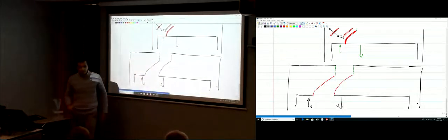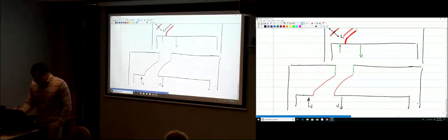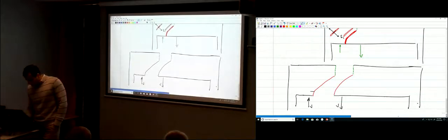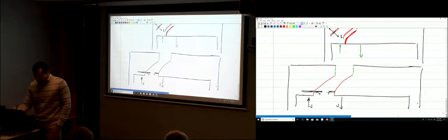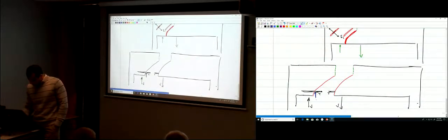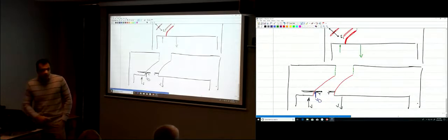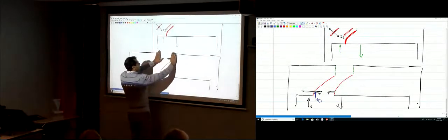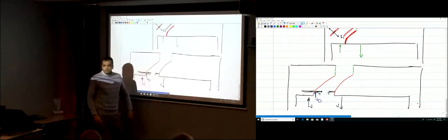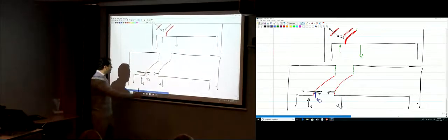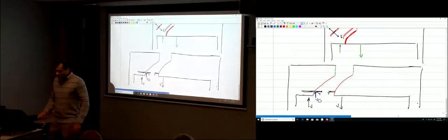Just stay on the top, compression concrete. Okay, so first here, you have some steel here that is under tension, okay? So there will be some dowel force here. We're going to call this VD, okay? This concrete over here is in compression, it's not cracked, right? The top part, the green part here, okay? It's in compression, it's not cracked.